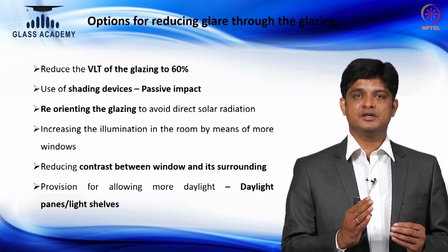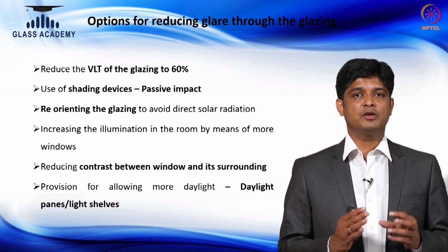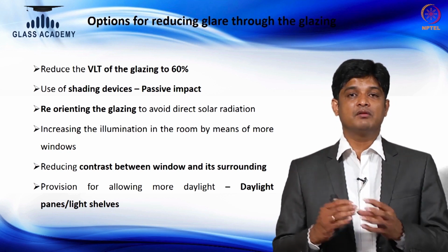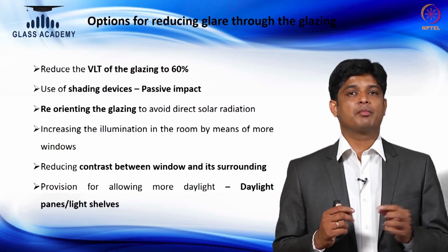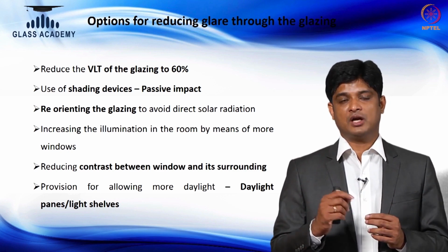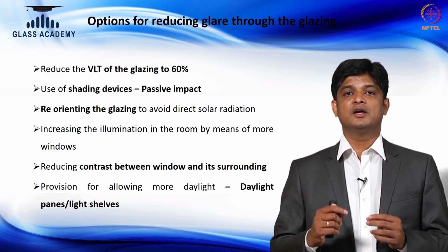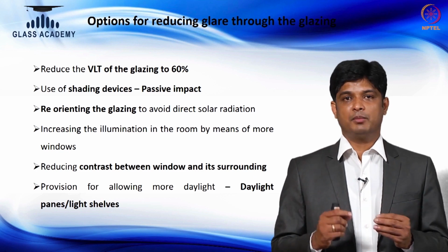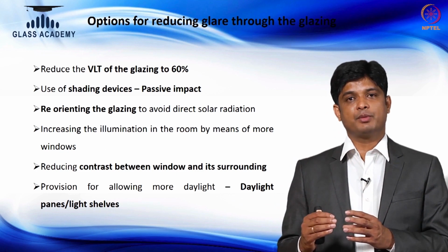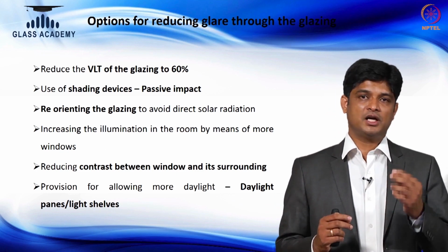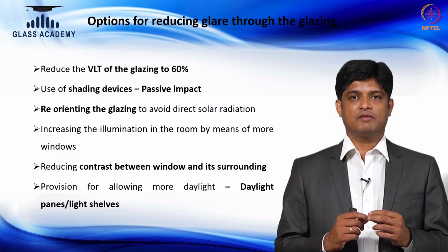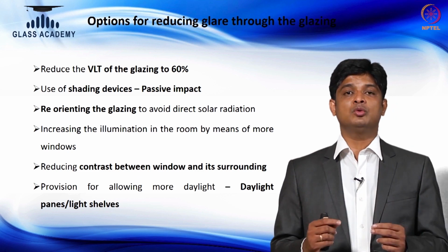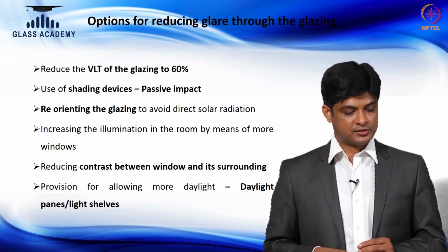As I said, to make a building ECBC, we need to find proper energy efficient materials so that the current design can be made an ECBC building. Whereas if I have to make ECBC plus, I have to do some kind of trade-off. It can be on the window wall ratio, it can be on the shading devices, or I have to introduce something like daylight shelves, or I have to introduce high performance glazing, which has a higher selectivity, to make the building ECBC plus. If I have to make a super ECBC building, then it has to start from day one, based on the orientation. Even orientation wise, the window wall ratios can be played with, or orientation wise different products can be used to make the building a super ECBC building.